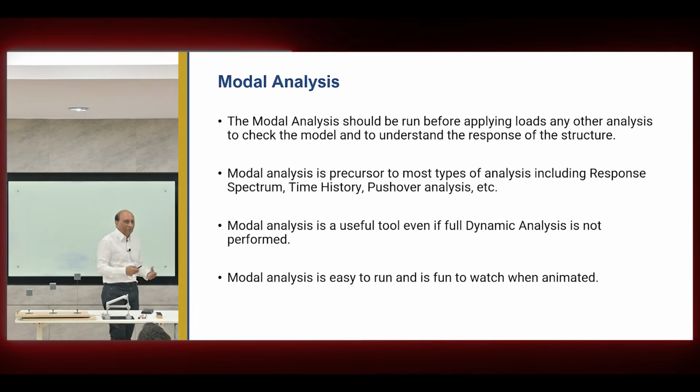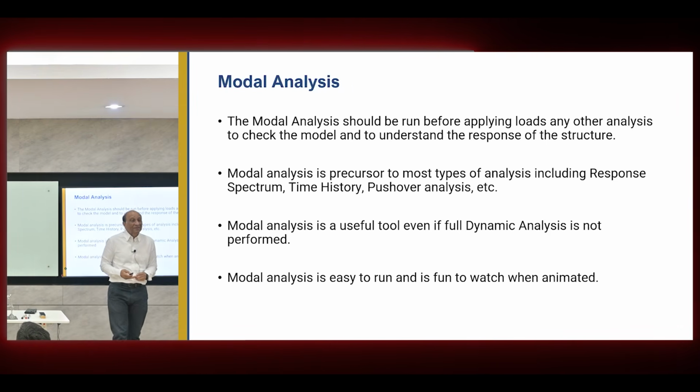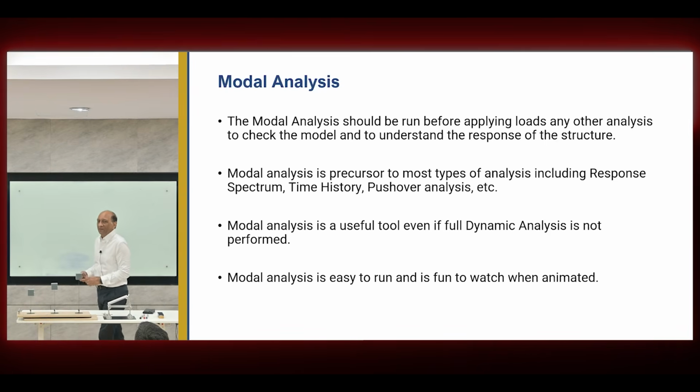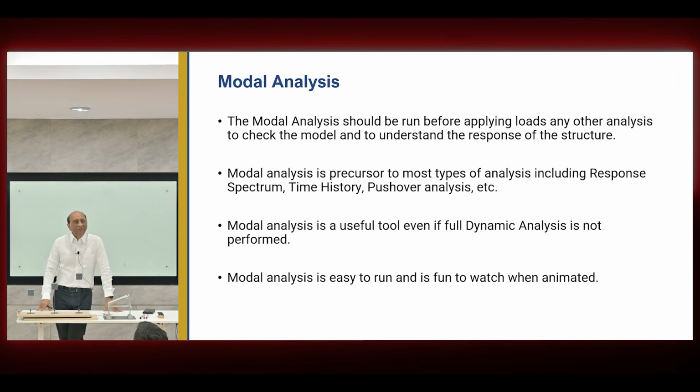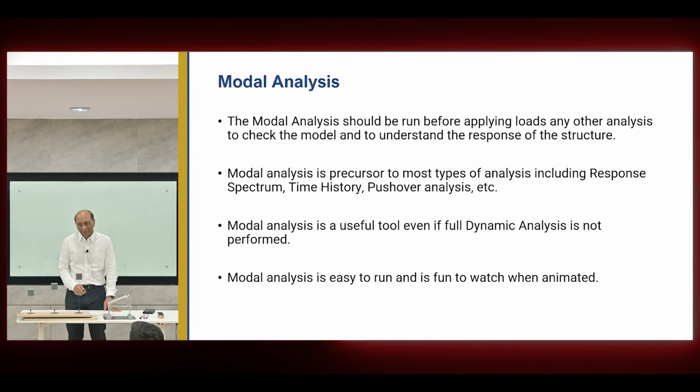Many people think, oh, I'm not doing dynamic analysis, I don't need modal analysis, because modal is a dynamic analysis, right? Kind of. But that's not true. Modal analysis is useful even if you do not want to do any dynamic analysis later. If you just want to do code-based design or whatever, modal analysis is extremely important. That's why we have a whole lecture dedicated to that.